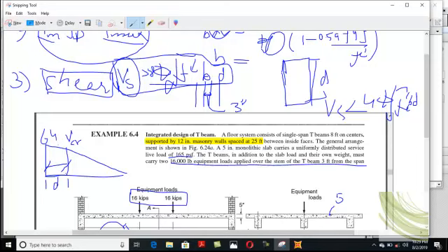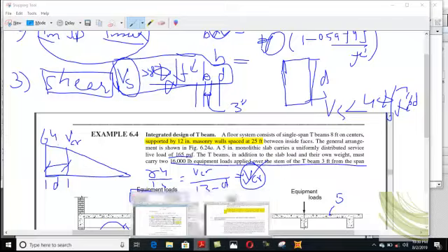So, at effective depth, using the similar triangle rule from statics, you can easily determine it. By similar triangle rule, 64 divided by the total distance, which is 13, equals this VCR divided by 13 minus this d. So, you will get VCR. That will be the critical shear, and this shear will be used in the shear force design. Clear? In the strip designs.